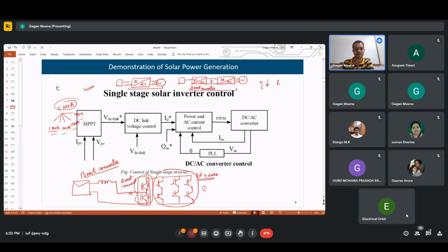So finally these signals will be generated for PWM generation, and these 6 pulses will be generated which will control the rotor side converter, and these 6 pulses will be generated for controlling the grid side converter. So the aim of the controller is to generate these pulses so that the switches will switch in a particular fashion to achieve the desired goal, to track these references.